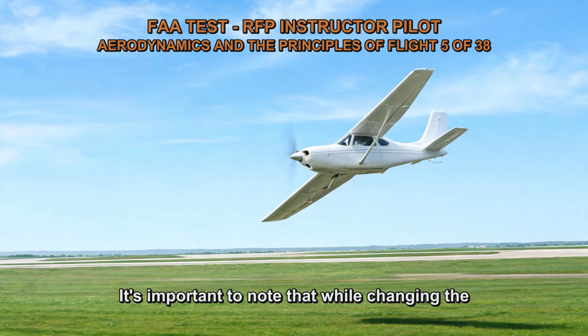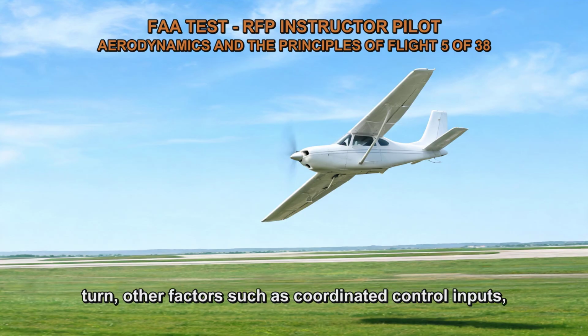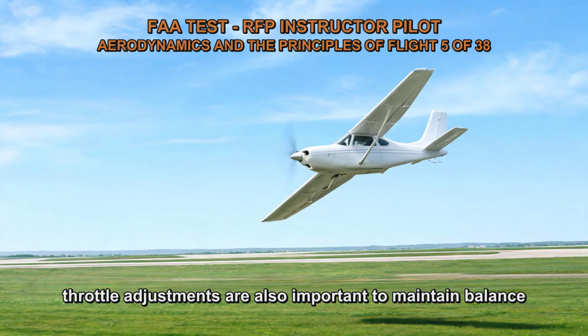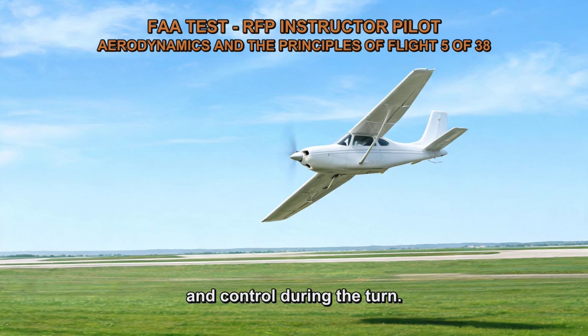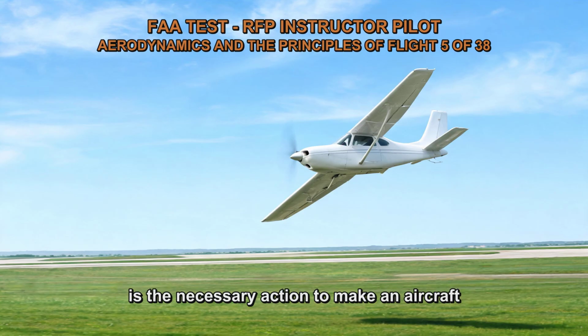It's important to note that while changing the direction of lift is necessary to initiate a turn, other factors such as coordinated control inputs, use of rudder for yaw control, and appropriate throttle adjustments are also important to maintain balance and control during the turn. So, in summary, changing the direction of lift is the necessary action to make an aircraft turn.